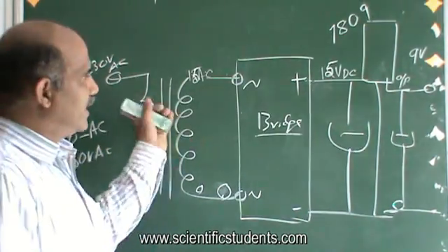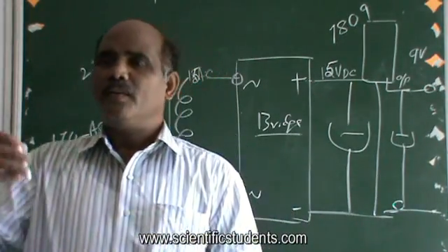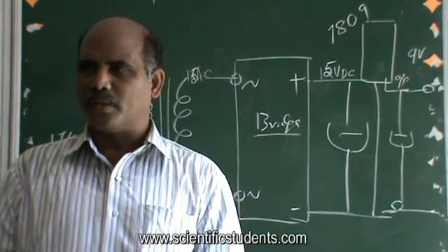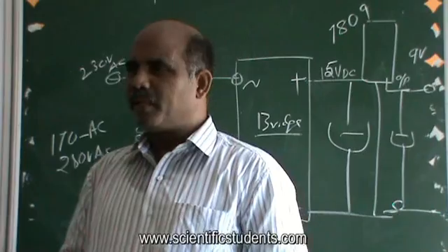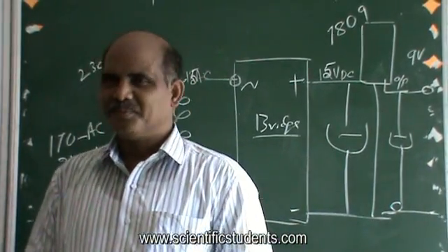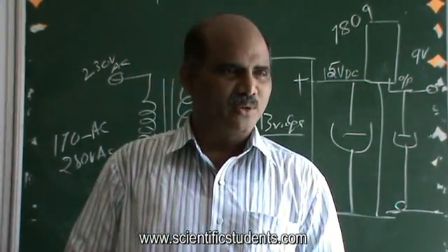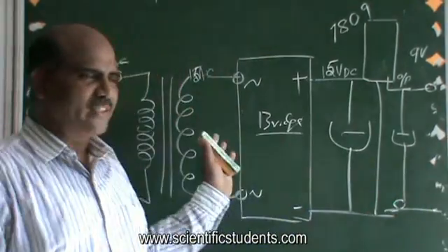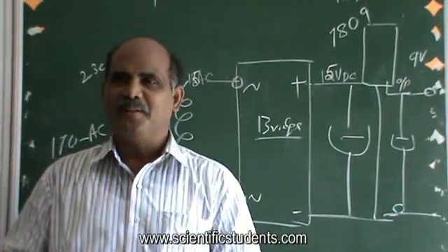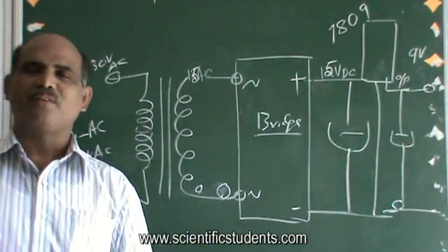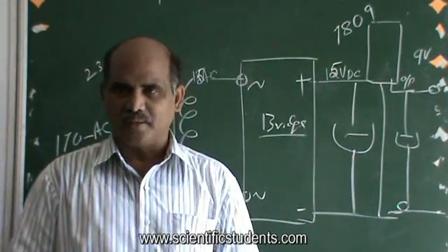Otherwise, if you don't design this way, Vinita may say, "When I use my project at my home, it's working, sir. But when I go to my grandparents' house, it's not working, sir." Why? Because the voltage there might be 190, while here in your home it is 230. At 230, she designed the transformer for 9 volts and everything works perfectly. But at her grandparents' house at 190, the output is around 7 volts. Then your circuit may not work properly.